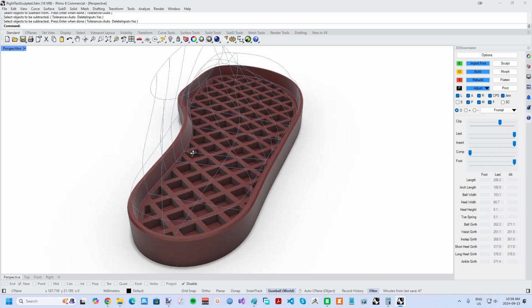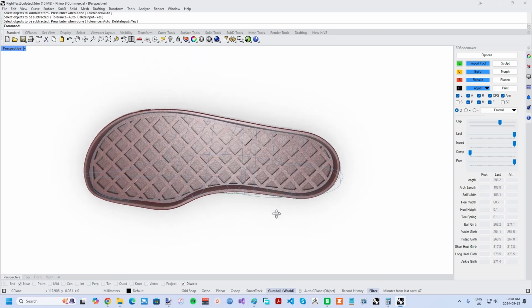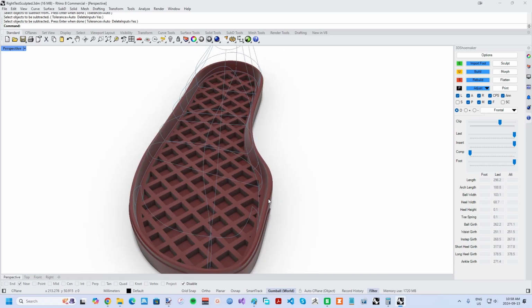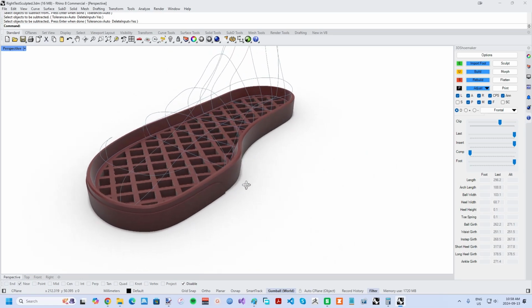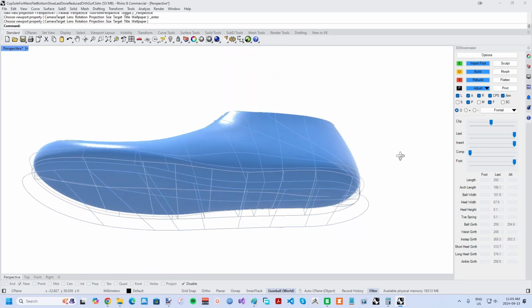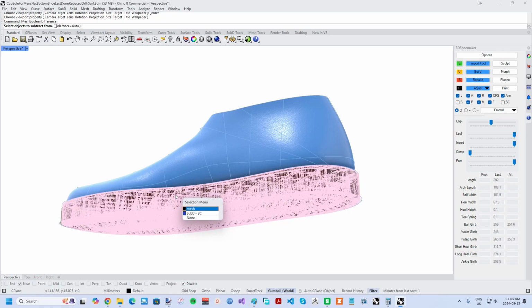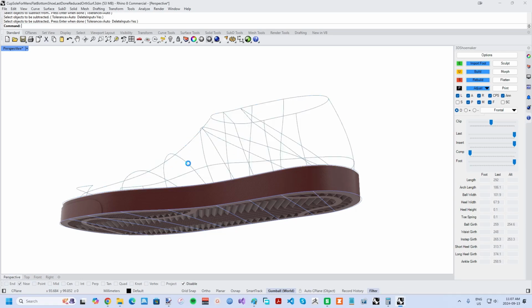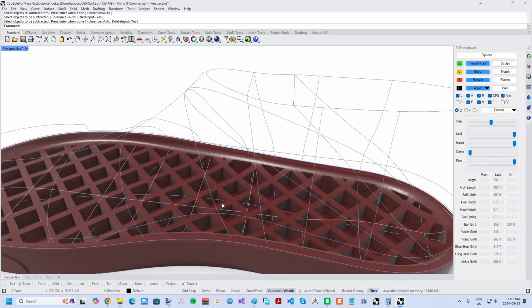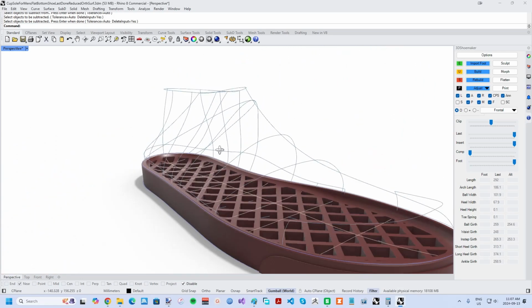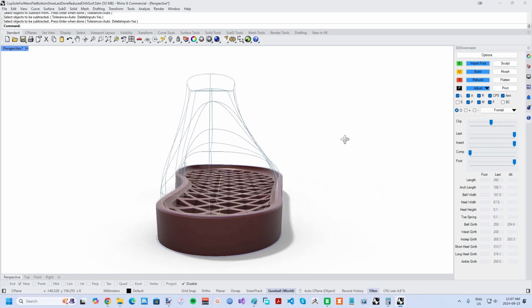The disadvantage is that wall thicknesses might not be perfectly uniform, but with sufficient cage density and iterations, it can come quite close. By subtracting the target shoe last after the fact, it can also be first trimmed by a custom orthotic surface to get a highly customized component. And if a gap between the component and the shoe last is required for upper materials, this can be achieved by first offsetting the sub-D shoe last by the exact desired amount.